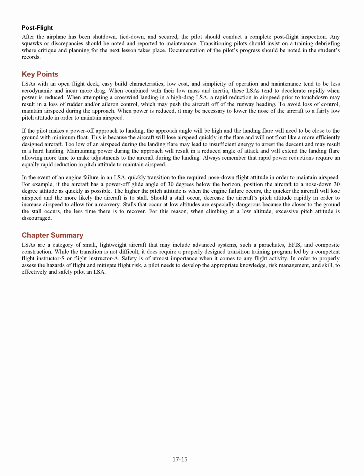Post-flight, after the airplane has been shut down, tied down, and secured, the pilot should conduct a complete post-flight inspection. Any squawks or discrepancies should be noted and reported to maintenance. Transitioning pilots should insist on a training debriefing where critique and planning for the next lesson takes place. Documentation of the pilot's progress should be noted in the student's records.